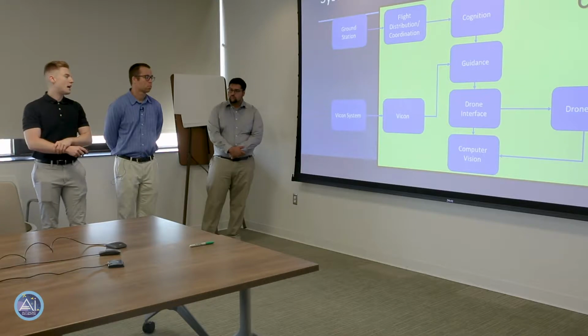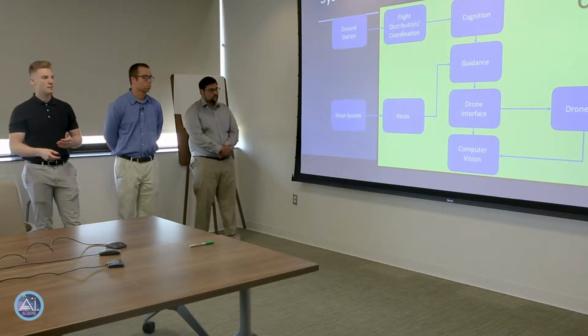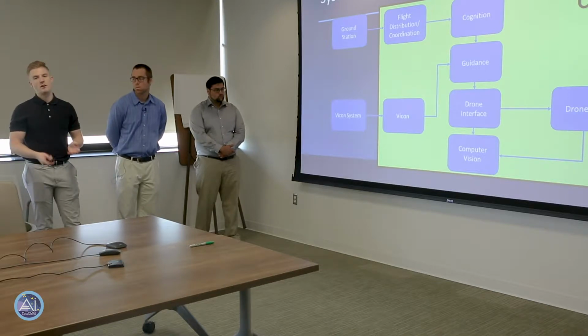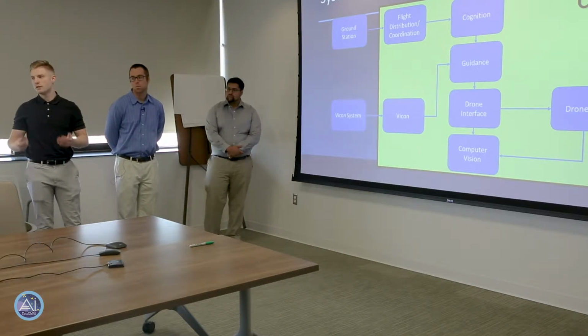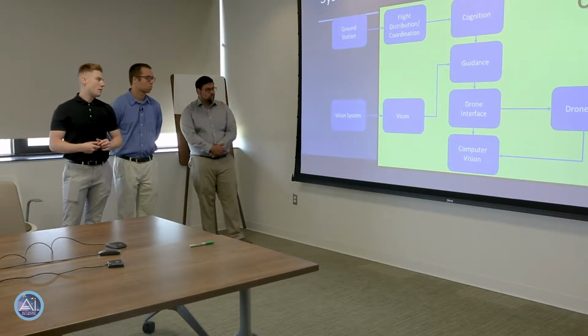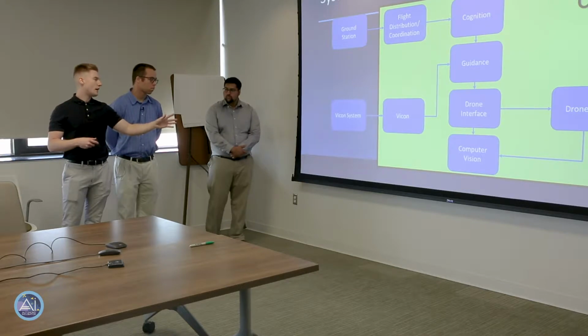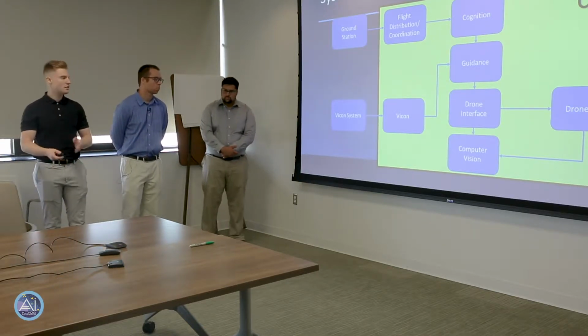guidance will also rely on a positioning system of some sort, and most of the time that could be GPS. ICAROUS requires GPS. However, in this situation, we don't have GPS, so we simulate GPS via Vicon. So we have a Vicon system, which will give us, I'm going to go over that a little bit more in detail after this, but it pretty much gives us the position information that we need, rotation, etc.